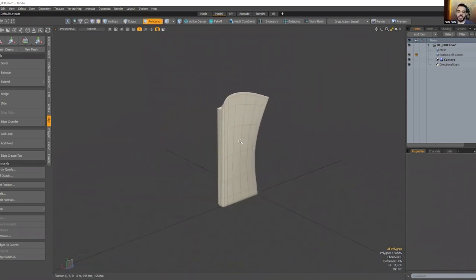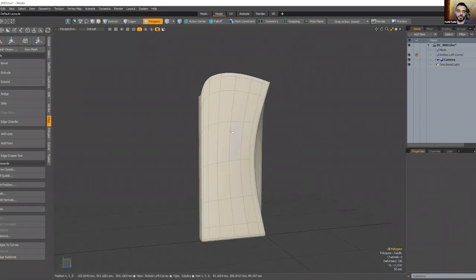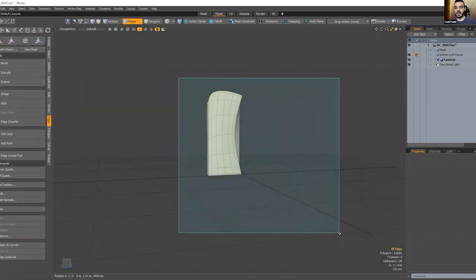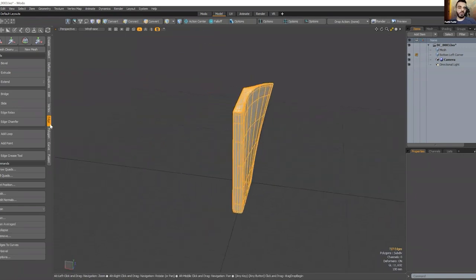And I'm going to go ahead and change the tessellation of that. If I'm kind of limited by the tessellation of the cubes or the squares or the rectangles here, I can change that into a different configuration. And the way I do that is first you have to select all the edges. So press number 2, that takes you to edges mode, and select everything, all the edges. So that's middle mouse button, select everything. And then go to